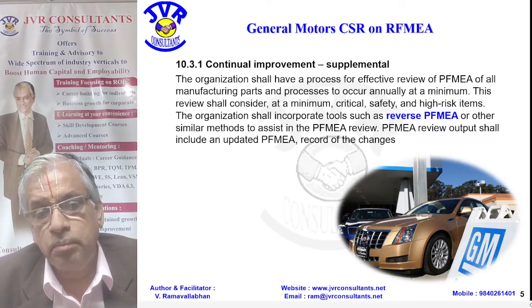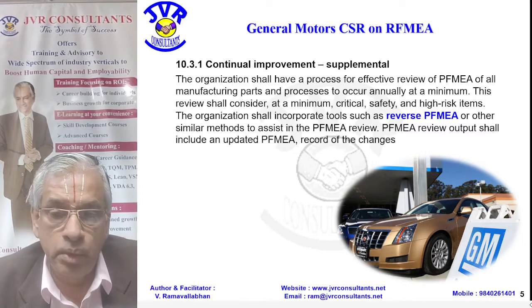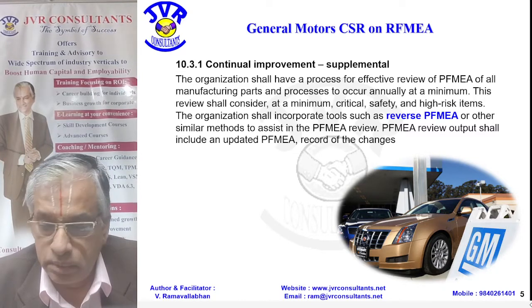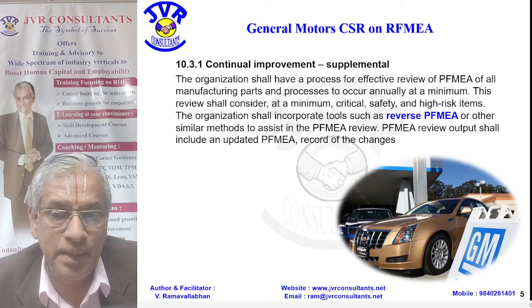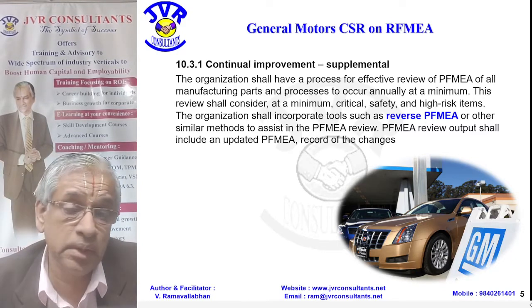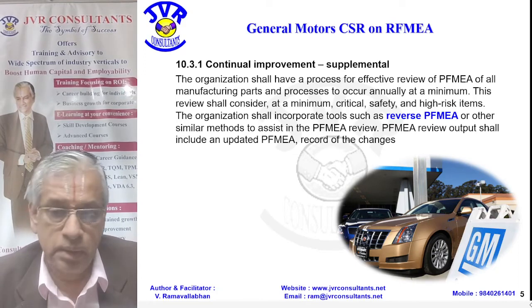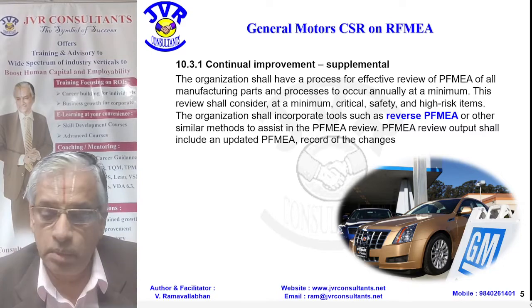So, at a minimum, annually you have to look into this. While doing this, consider the product's criticality, safety, and high risk. Considering this, carry out this reverse FMEA and whatever you have done, get it updated in your process FMEA.